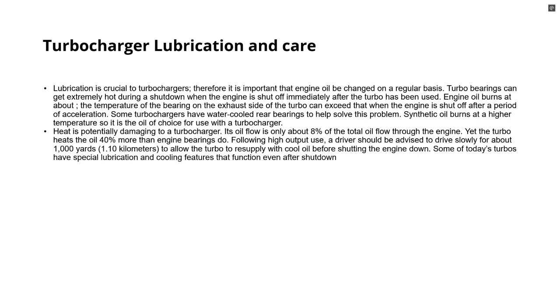Lubrication is vital to prevent turbocharger damage from high temperatures. Regular oil changes and synthetic oil can help manage extreme heat. To prolong life, allow the turbo to cool down with light driving after heavy use. Some modern turbos even have features to provide post-shutdown cooling and lubrication.